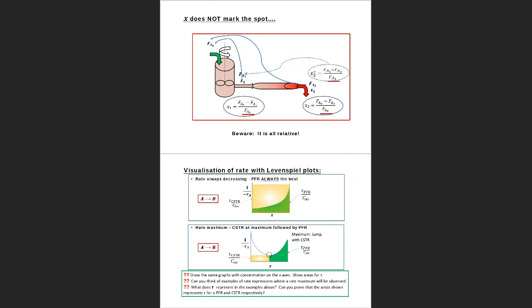Okay, right, so X, conversion. I am sure Dion or Dr. Brink tested you on this: be careful with conversion, with X. It is always based on a molar flow rate. So if I want the overall conversion, I will use the molar flow rate out relative to the molar flow rate in. In some of the TATs and the online tests, I'm going to separate a stream off here. So, I take off a little bit here. Please calculate the overall conversion.